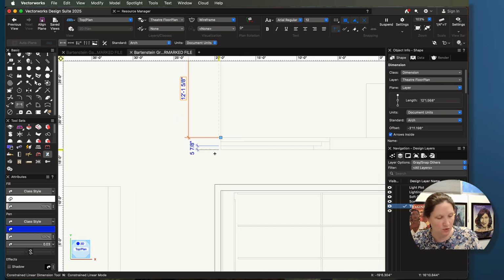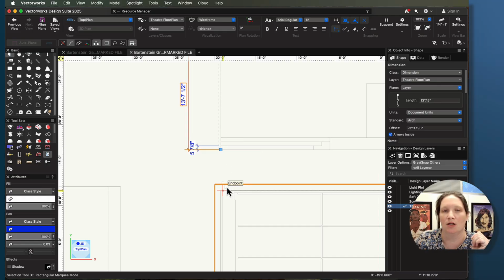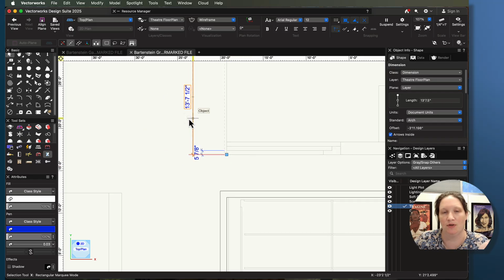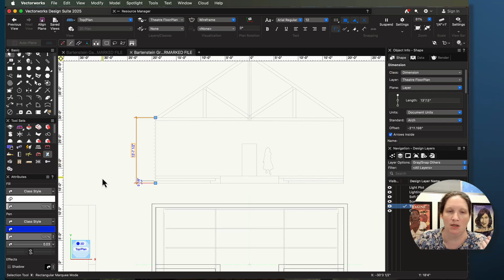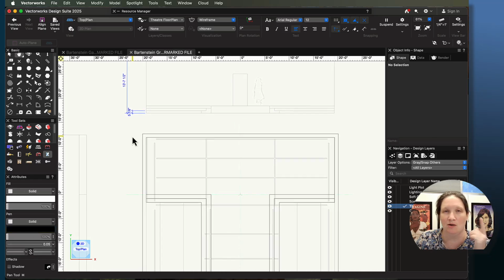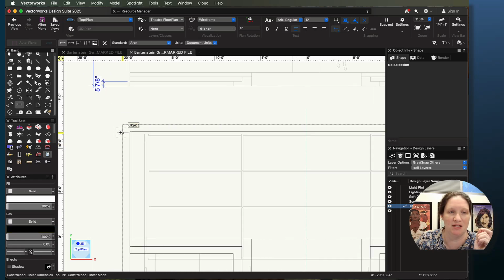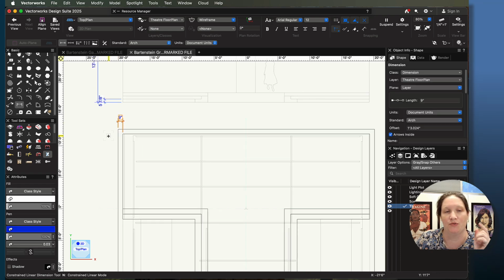Or actually, we'll extend it. We'll extend our walls starting below the stage height so that they actually fill all of that space. So that's 13 foot, 7.5 inches is the measurement I just got for the walls. We'll remember that for later. The other relevant measurement is going to be the thickness of the wall, and it's a 9-inch thick wall. So that we need now because we're going to go get our wall tool and build some walls.